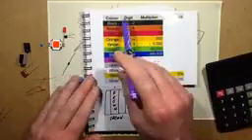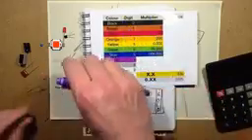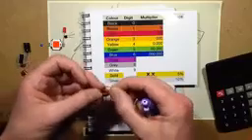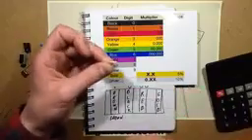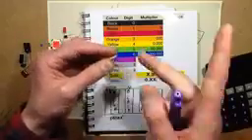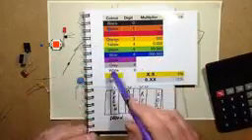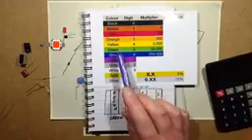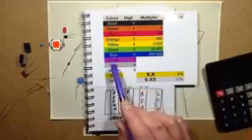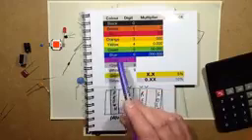After you've been using resistors and reading the colour codes for a while, you'll just look at a resistor and go, 1K. Just look at it and instantly know the value. It's how it is. The same colour code is sometimes used on older capacitors, and it's still used on inductors, which look very much like resistors.